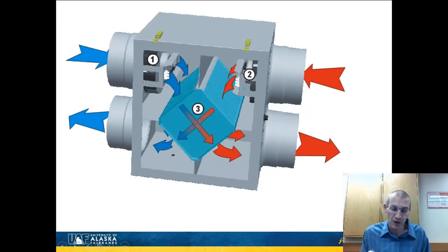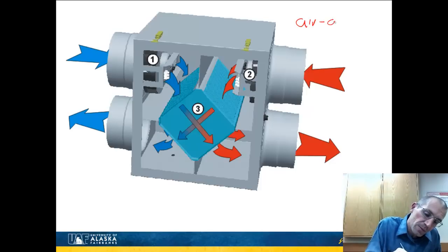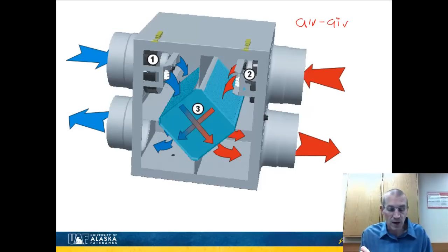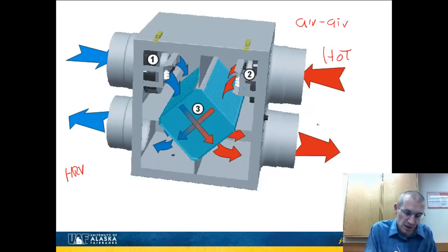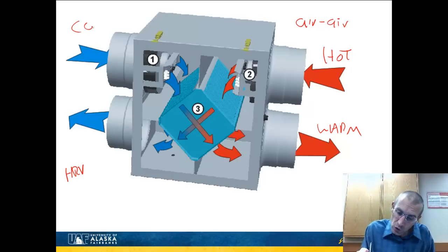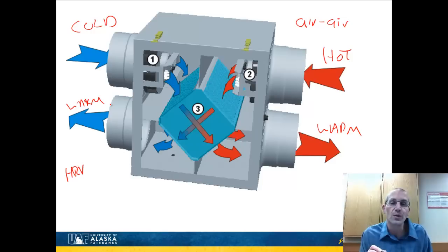Here's one more type of heat exchanger, and this is an air-air heat exchanger. And this is pretty common in residences. In fact, this would be a heat recovery unit or heat recovery ventilation system, or HRV, where the point is you're moving air out of your house so your air doesn't become stagnant, but if it's cold outside, you want to recover some of that heat. So here we have hot air from inside the house, and it's leaving somewhat warm before it gets dumped outside. Here's the cold, fresh air that's coming in, and it's going to leave somewhat warm and will eventually go into your house.